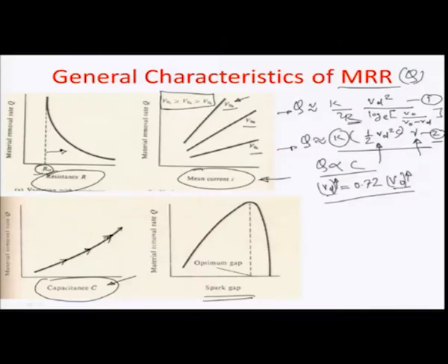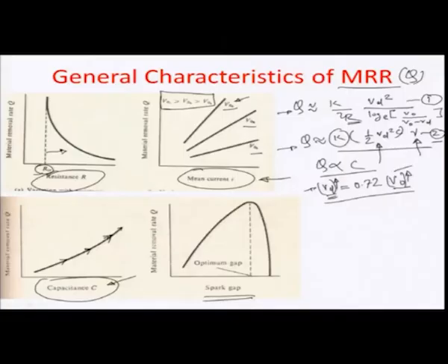Actually, it is a cause and effect question: which is the cause and which is the effect? Basically, discharge voltage is the independent parameter, which depends on various properties of the gap, the dielectric of the gap, the dielectric constant of the gap, or the gap itself. Vd is really that point of voltage which starts the discharge, and so VO has to be set in accordance with this Vd.